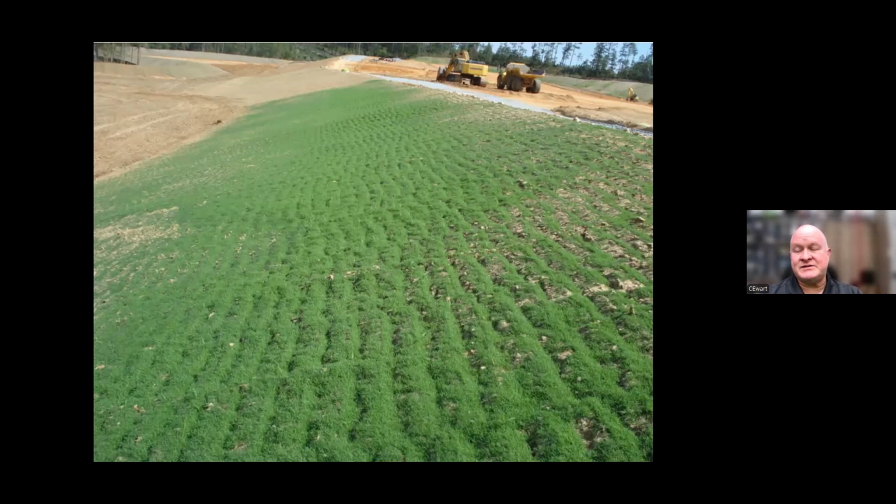So in those areas, perhaps there's an issue where there's some kind of contamination in the soil. We've seen areas where a slope doesn't have any vegetation growing on it, and it turned out that that was the area right beside where the concrete washout was, and perhaps the pH of the slope in that area is contaminated. So again, things can be done to fix that and correct that before you get into major storm events.